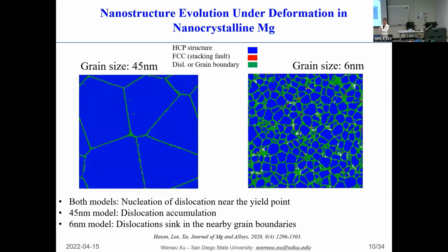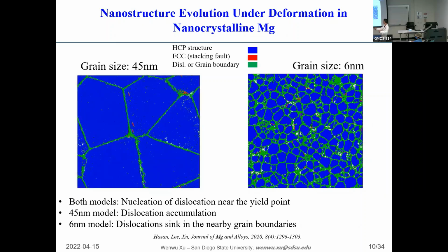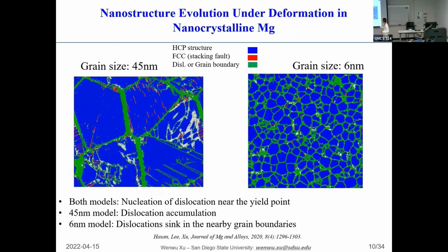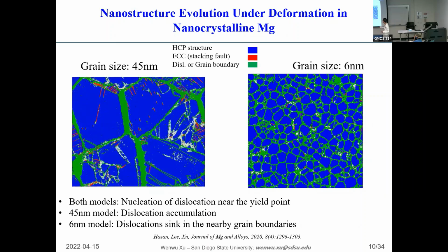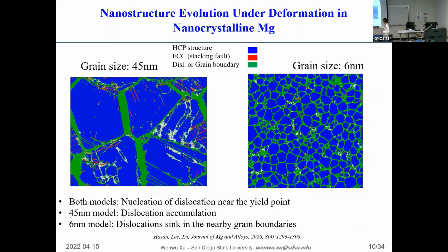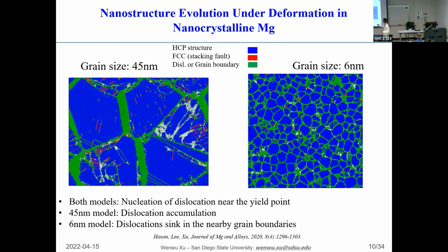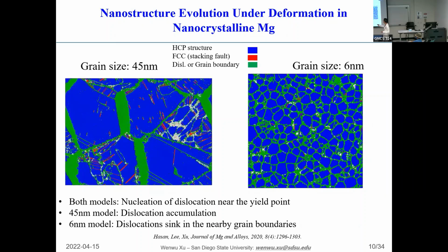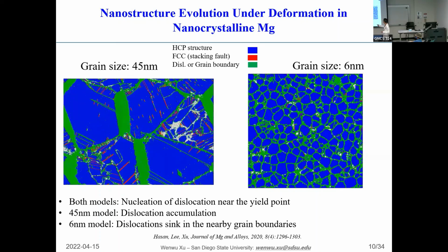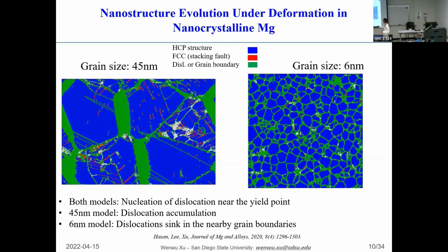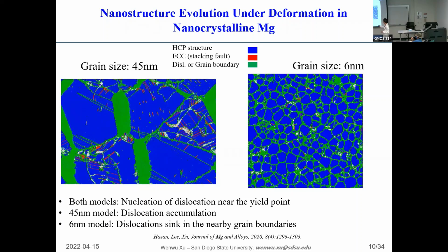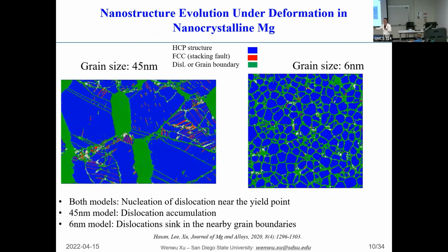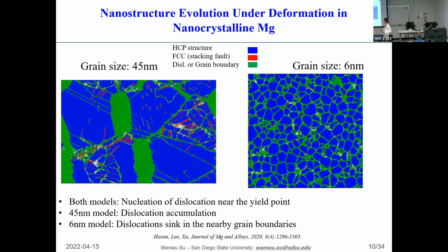And then initially there was nothing because it's still in the elastic range. And then once it crosses into the plastic range, we can see a lot of things happening, like this grain feature that is moving across the grains, including this region, and we would also see this feature moving across the crystals, and it's actually accumulating more and more when the plastic deformation is slowly happening along this direction.